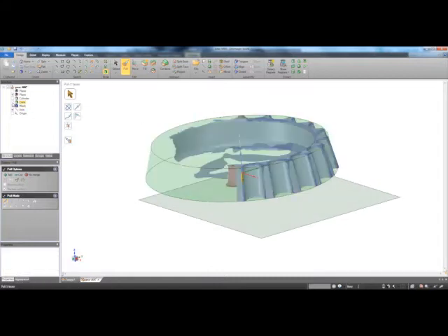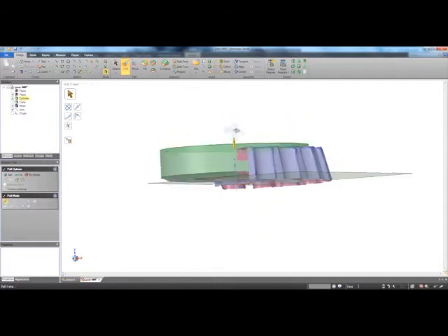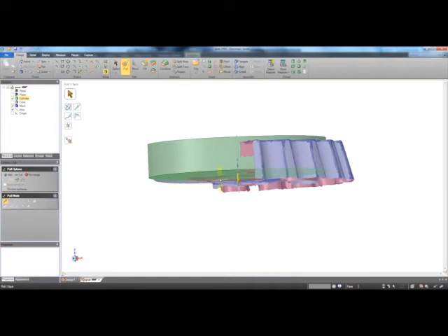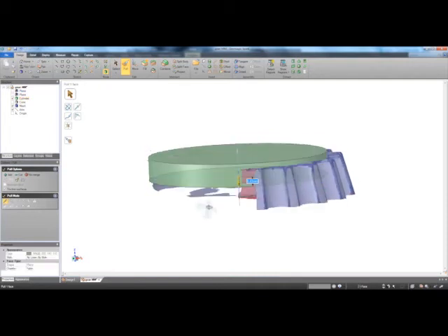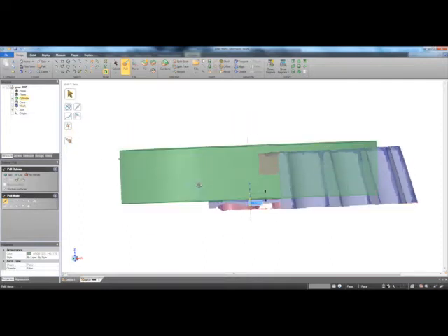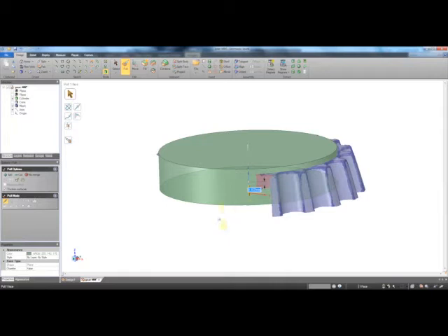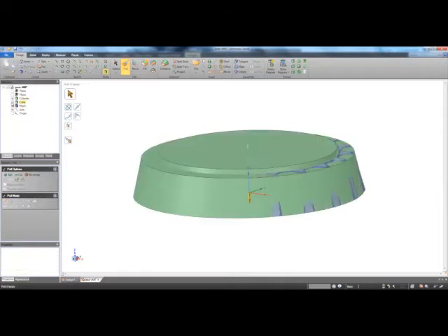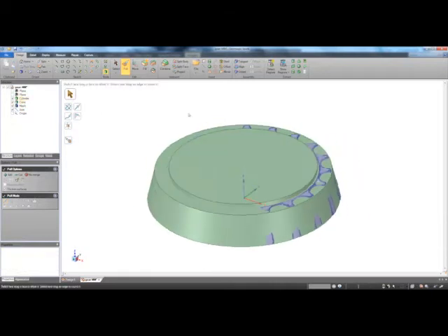So let me hide that cone and I'll show the cylinder, and inside here I can do the same thing. Let me hide that plane as well. I can take that bottom face, I can move that. If I want to snap it to this surface on the mesh, I just say up to, click on there, and so now that bottom surface is in line with the mesh. I can show my cone, which is my main body, and now I can combine these two together.